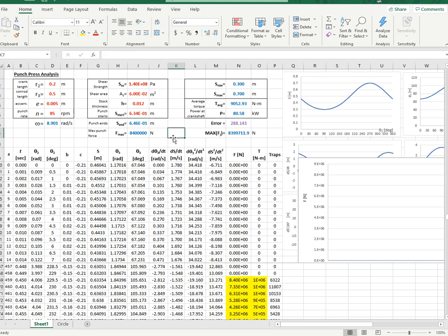When the punch ends would be when the punch starts plus h. And then the maximum punch force. You go to the notes on flywheel, the chapter on flywheel design, where I'm explaining how you essentially define a linear function corresponding to the beginning and end of the punch, so maximum force at the beginning and zero force at the end.